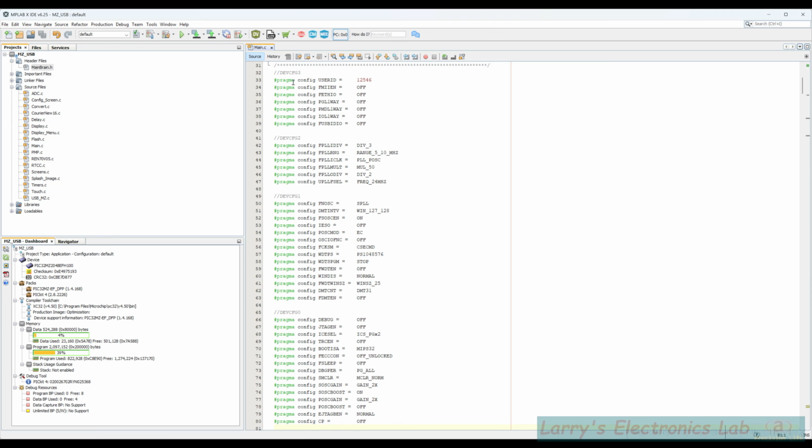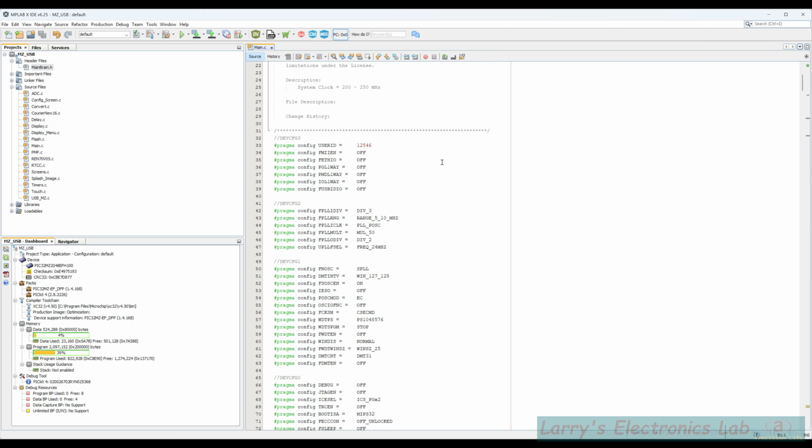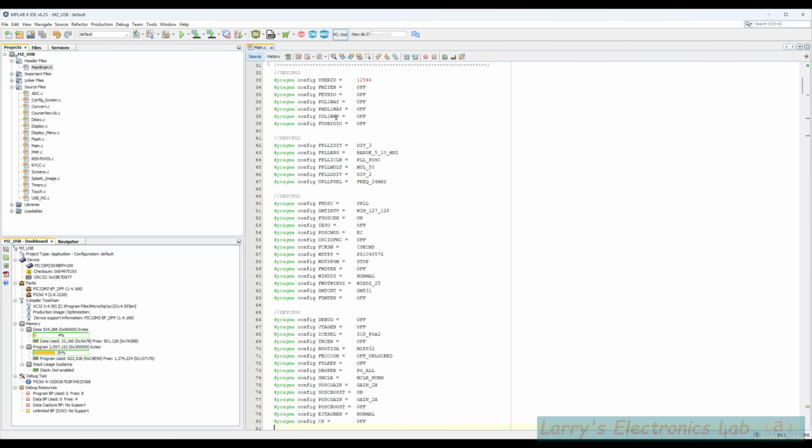Now, this is the exact order that the hardware, the microcontroller, loads all these bits. Well, at least the blocks, but I'm pretty sure this is the order of the bits as well. And you can't change that. Moving these around does not change the order in which they're loaded. It's set by hardware. The reason is that if a bit down here happens to change something up here, then it's in the right order so it doesn't cause some kind of hardware lock or some problem.